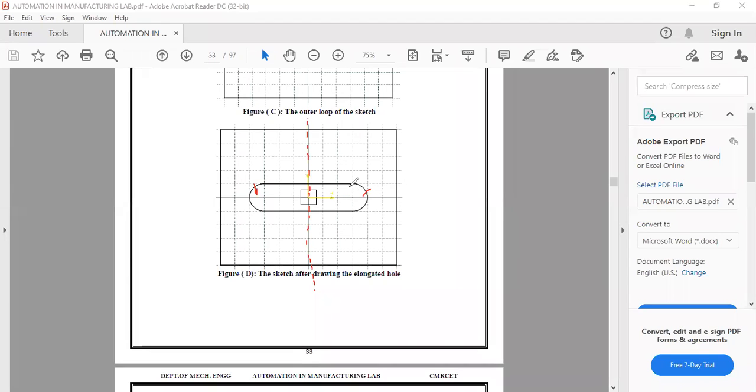And about this one also, you can take this standard axis, it is already there, no need to draw it again. Firstly select these two lines and then this axis, go to the constraint defining dialog box and make them symmetric. So that's how you can do that.